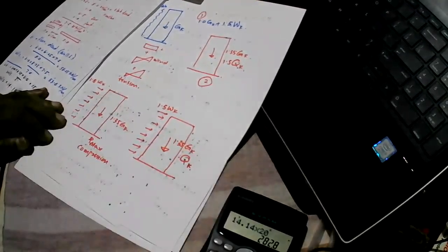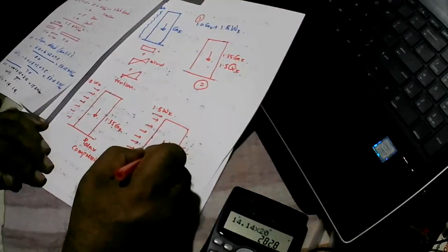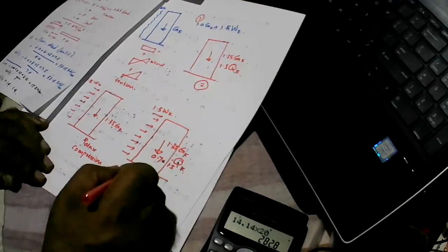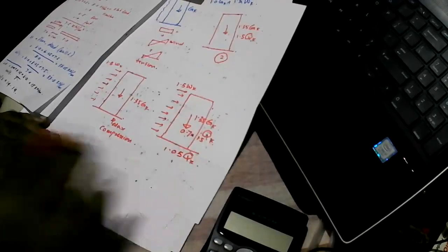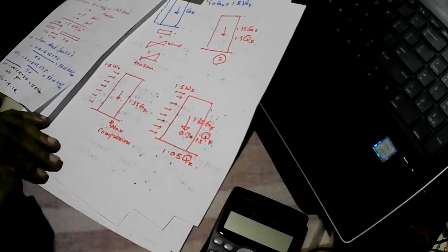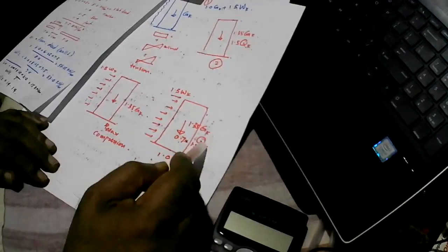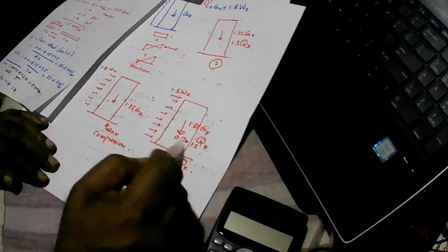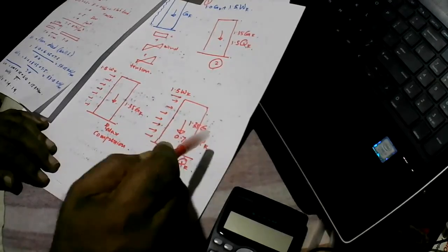What is the factor that we get for Qk? So this should be 0.7 into 1.5. So we get 1.05 Qk. The reason is we can't have two primaries, so this will be secondary, which means we have to multiply the imposed load by 0.7 to get this effect.